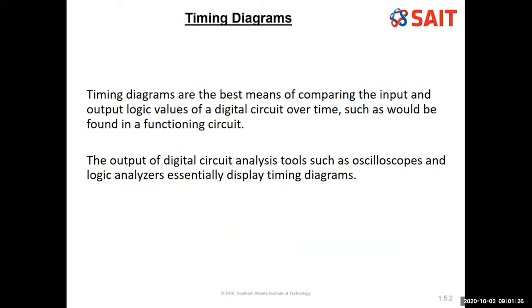We can analyze a circuit, we create a circuit, but the things we're creating, even though they're digital circuits, they're still made by real world items. To look at a pure Boolean circuit, it's still a silicon-based circuit. It still has microwelds. It still has potential defects. It still has soldering in it. It's a real world item, and no two things will perform exactly the same. So sometimes you run into issues where a circuit does not perform as expected, and we use timing diagrams.